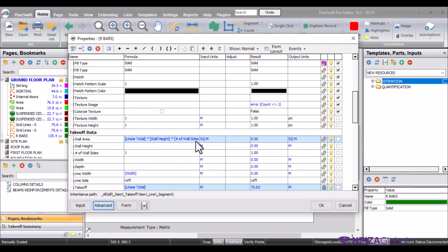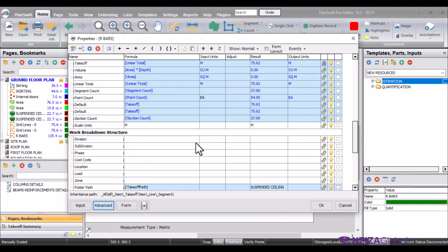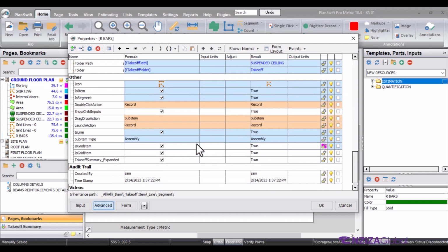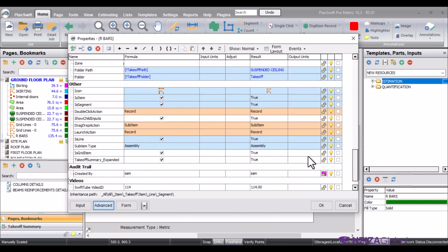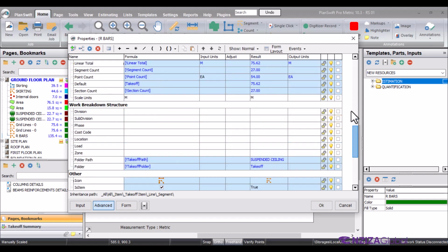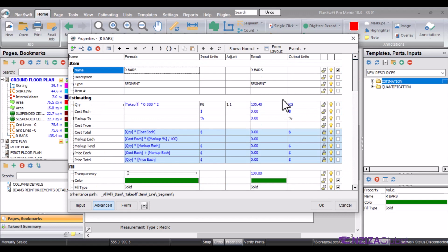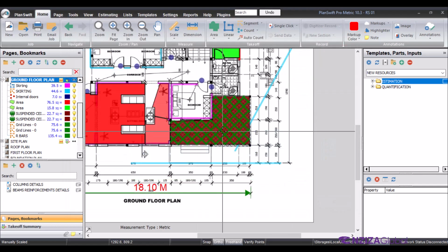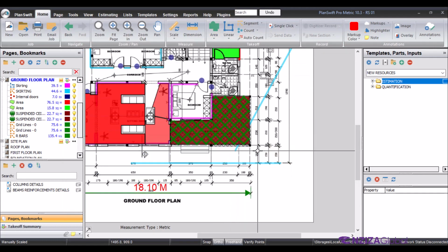You can adjust all of the spacing from 600 maybe to 200, so that you have information which is more reliable on this type of takeoff. But I just wanted to show you how you can use these grid tools to measure for the mesh reinforcements in slabs and other horizontal reinforcement slabs as well.